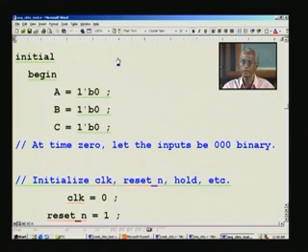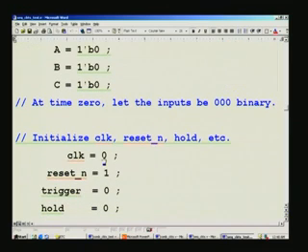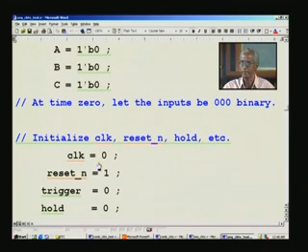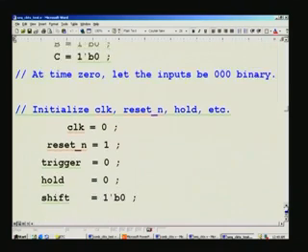Clock is actually a variable here, it is a purely behavioral statement, not an RTL coding conformation. It violates RTL coding, because it is only to create a clock for the sake of the simulator. It is not the actual chip level clock which needs to be generated separately using another IC or whatever.